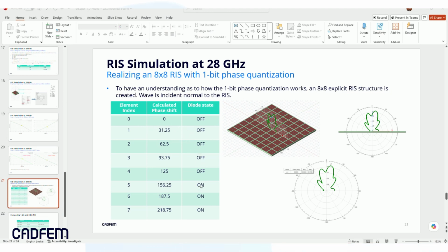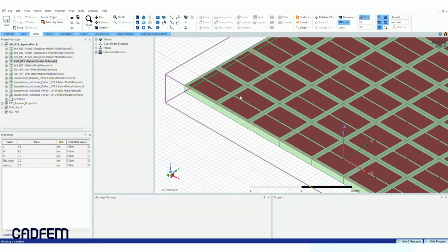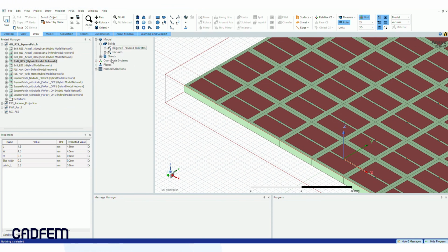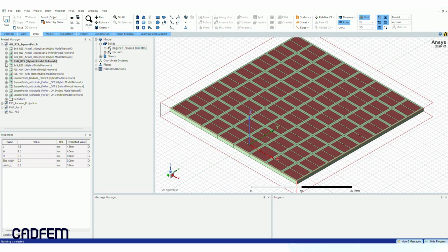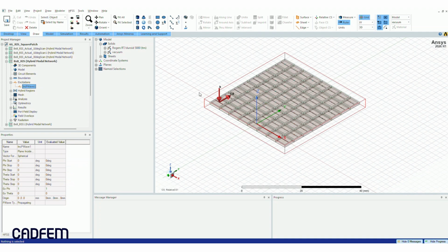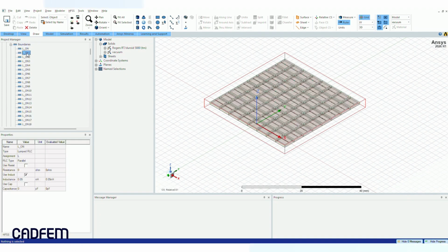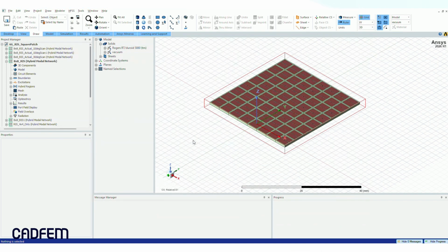Once calculation wraps up, we return to post-processing to evaluate our phase characteristics. We generate a fresh rectangular data report, plotting the return loss phase response across our frequency sweep. By placing a data marker at our 28 GHz center frequency, we extract an absolute response of 137.5 degrees. When mapped against our previously extracted data of -41.5 degrees for the alternate state, it confirms that our desired wideband phase delta of 179 degrees has been perfectly achieved.